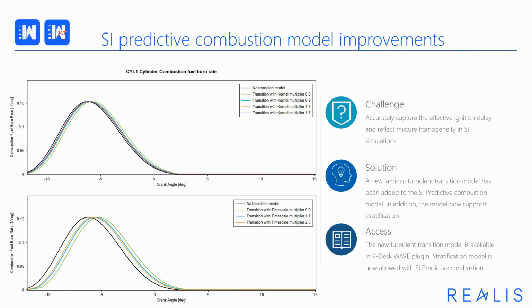In addition to this development, we also have enabled stratification model with SI predictive combustion, so these two models now are fully compatible. And this integration helps our customers to represent incomplete mixing and charge distribution more effectively and accurately for direct injection applications.